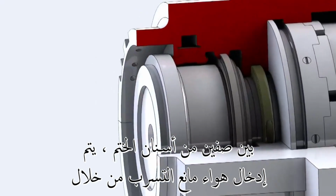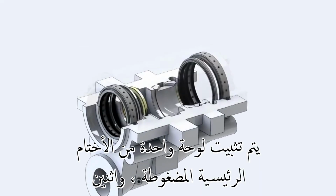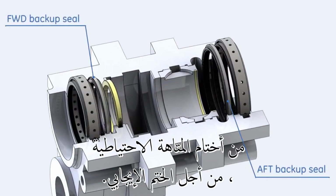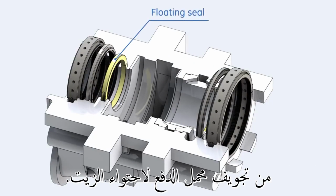Between the 2 rows of seal teeth, sealing air is admitted through multiple radial holes to stop oil from spreading along the shaft. Some of this air returns with the lube oil and is vented through the lube oil mist eliminator, and some escapes out of the housing. Inboard of the main pressurized seals, 2 backup labyrinth seals are installed for positive sealing. A floating seal is installed on the forward of the thrust bearing cavity to contain the oil.